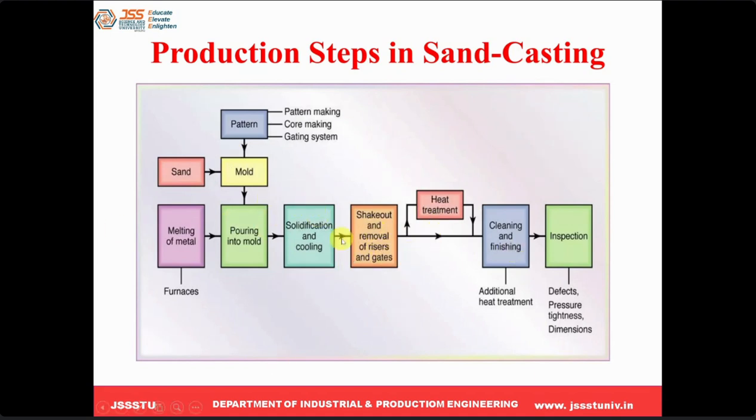Then further machining process we have to do, and any heat treatment process we can do, and finally we go for cleaning and finishing, and finally inspection to find any casting defects. This is the sequence of process of sand casting. Clear?